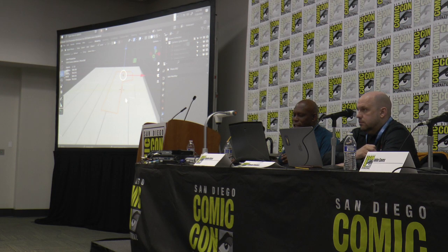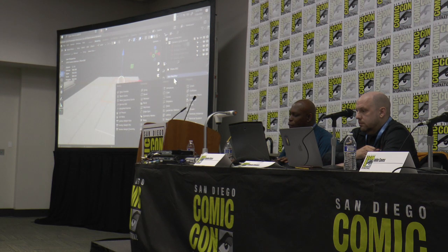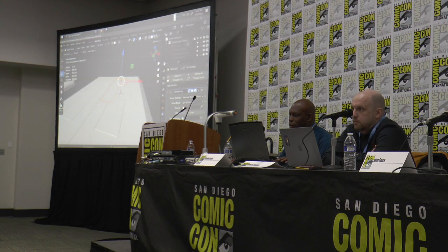I want this to be sitting directly on the surface of my ship. Modifier, deform, shrink wrap. Shrink it to what? There's my target, eyedropper, click on this ship, boom. It can be curved, it can be doing whatever you want. It will shrink wrap to that surface.